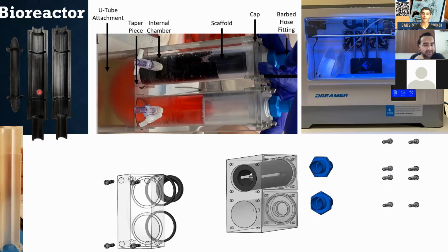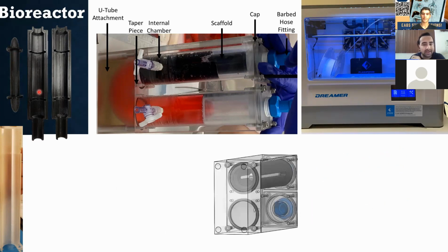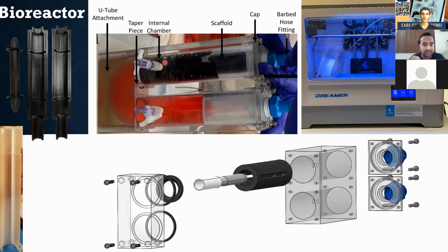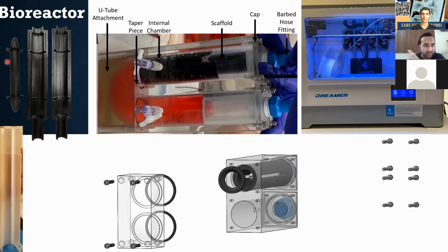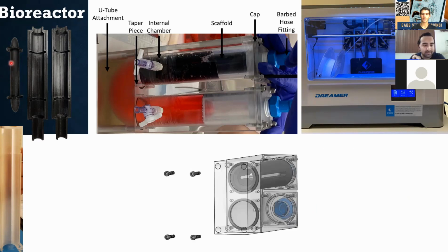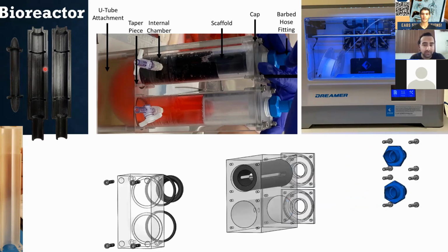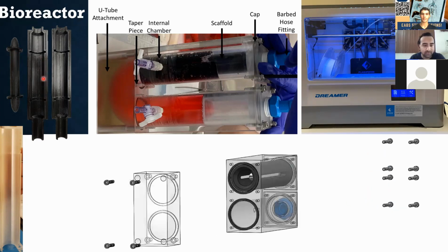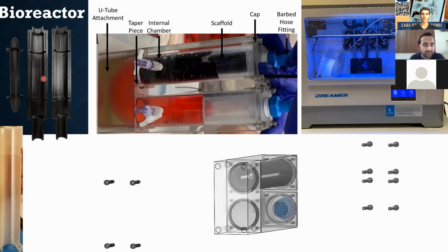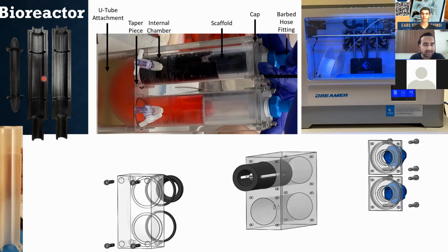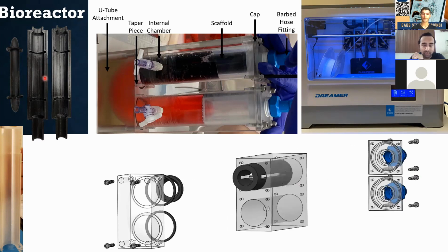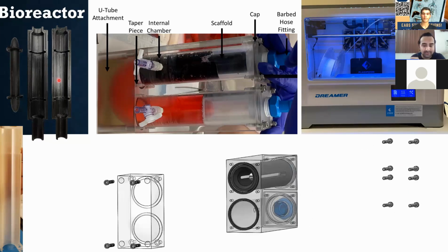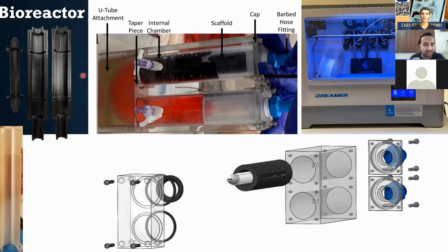And it's vital for my application that it's exactly 3 millimeters because I run fluid simulations, and having a gap of that 3 millimeters or whatever is the perfect gap I need to induce the fluid conditions and the shear stresses and the velocity contours I require that are most favorable for cell growth. So I take the tolerances as far as 0.1 millimeter differences really strictly. That's why I was emphasizing them throughout the presentation.